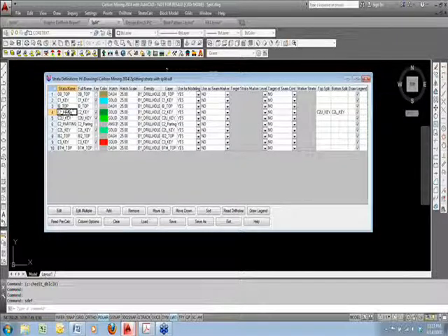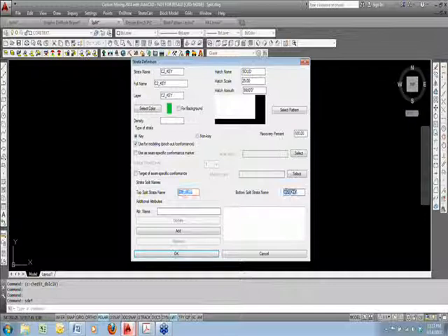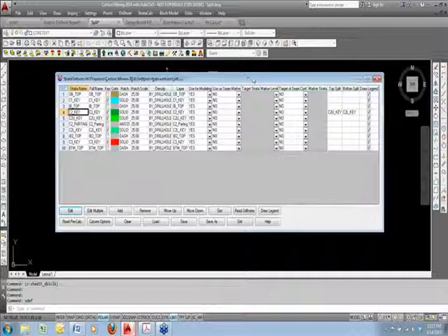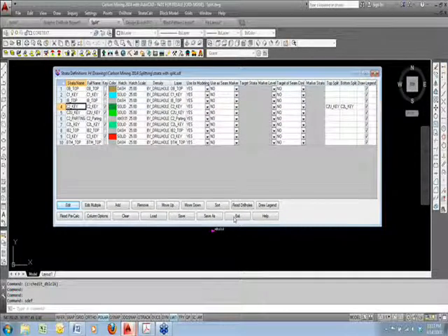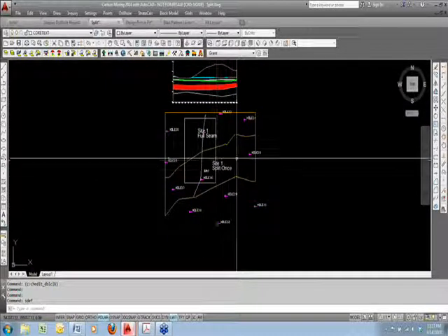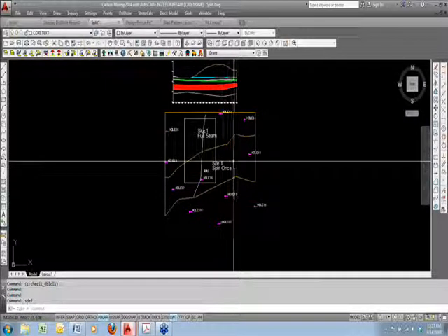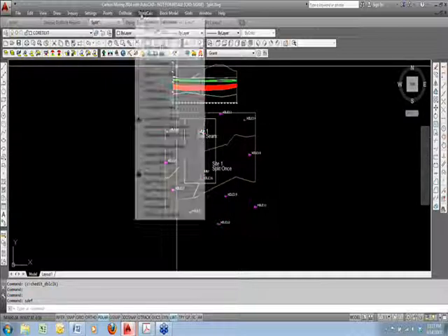The typical definition is the C2 parent is defined to split into the C2 upper and C2 lower. Now that's not new, that's always been there. That way it correlates the roof and floor of the C2 parent to split into these smaller children's seams. What's new though is we would model this the same as always where it's split everywhere. But then when you run surface reserves or you do any other model analysis and even fence diagram, it automatically joins them back together based on the parting thickness.